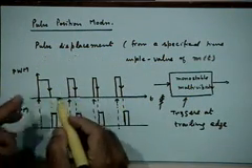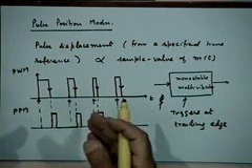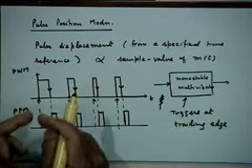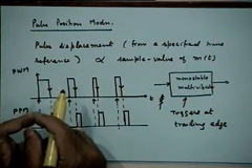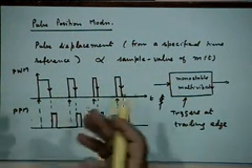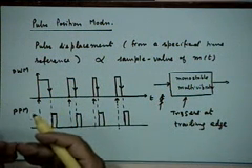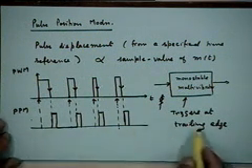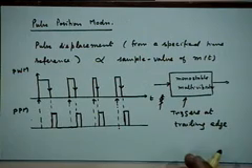Suppose, see, this 1/2 fs maximum width I talked about was when you are transmitting only one signal. Suppose you are transmitting 10 signals, then the maximum pulse width you can have is 1/20 fs, because this second signal will also take its range of pulse widths, right. So the pulse width that you will end up using will be finally dictated by the number of signals you want to multiplex in time. Okay. So that is a ppm signal. That's how you can generate a ppm signal.